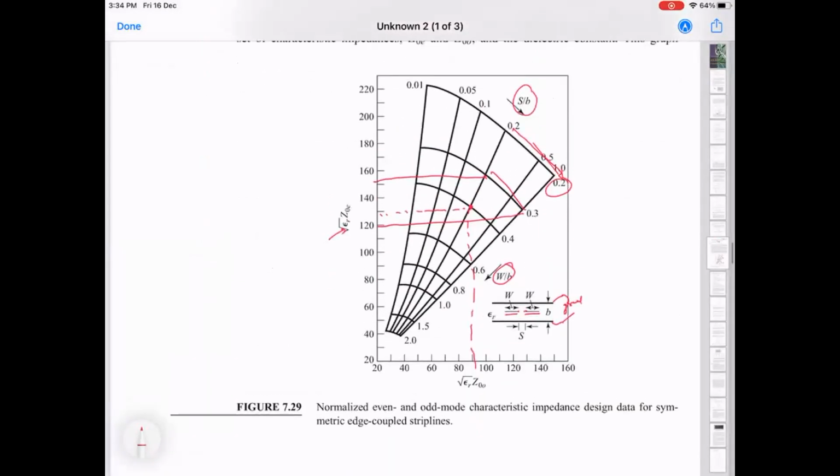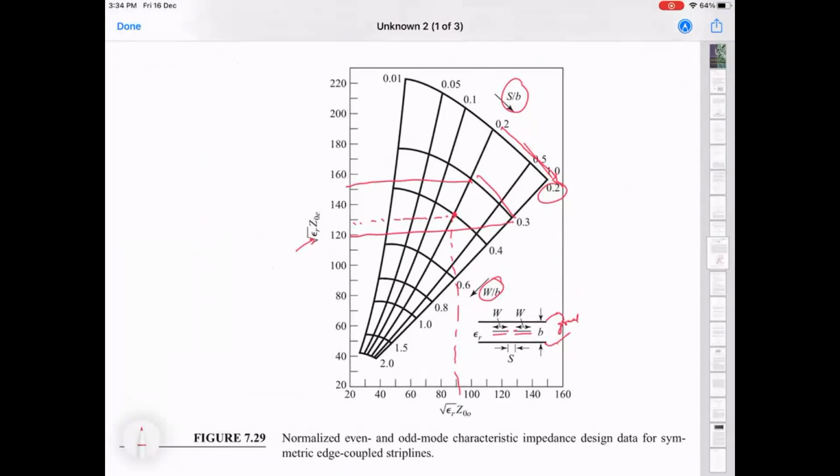So essentially, I think the general point is that both capacitances sort of go up as you bring this together. So impedances come down as you. The change should be symmetric if any change happens. And actually, no, sorry, but that's opposite of what is happening, right? No. Because if the capacitance goes up, it's sort of the other way around, because I guess because there's some extra capacitance going to the odd mode, the even mode capacitance is actually effectively decreasing.